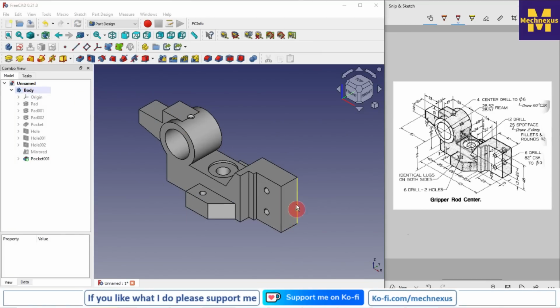As you can see that we have completed our model, and here is a common note which is a round and fillet of R2. So you can give the fillet to the all around the part of R2 radius, and this is how we have made gripper rod center 3D model with respect to our drawing in FreeCAD with the help of a part design workbench. Thank you for watching and thank you for your valuable time.